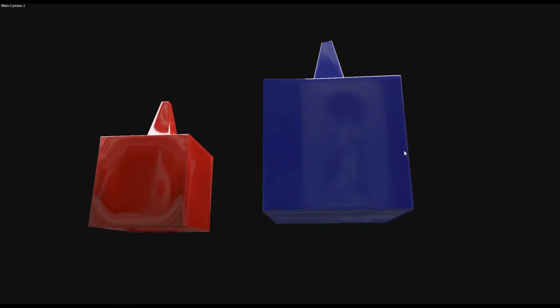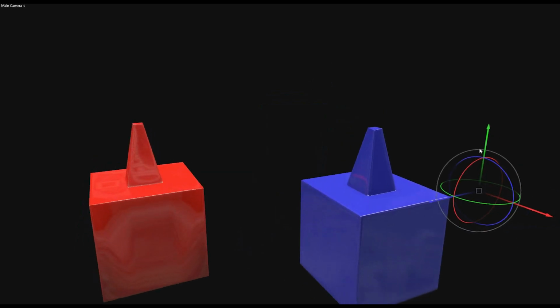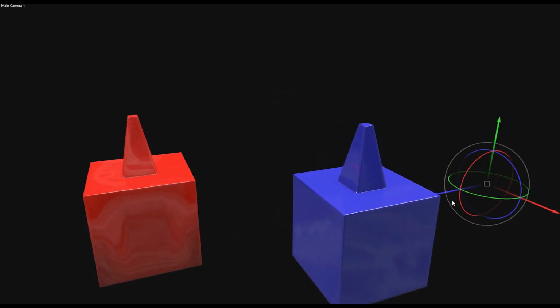But if we come down here on the bottom side, you can already see what's going on. Over here we have this nice smooth transition, that high poly look. But then if you come over to here where I had skewed it off, we actually lose that smooth transition. And that's because the normal map is actually baked in the wrong location and it's low. If I come up here, you can actually see where that smooth edge was recorded down, which is right here. That dark area should actually be up along here.